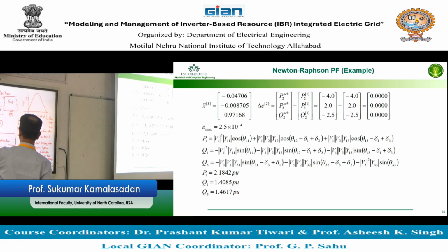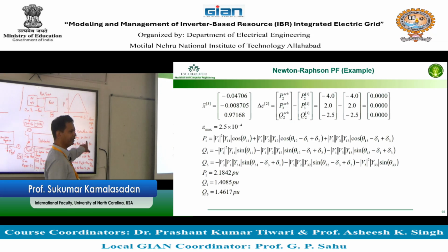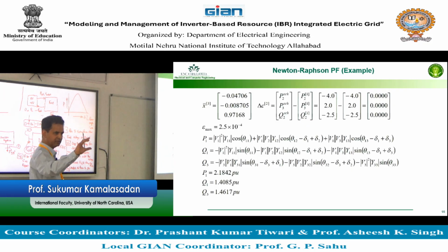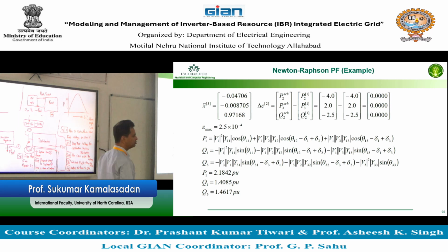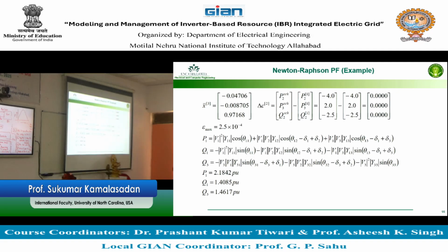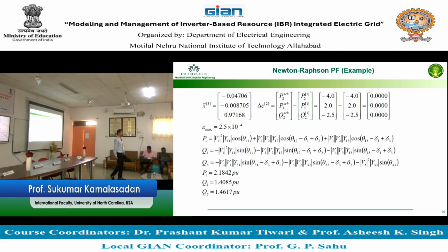And then repeat step 1, which is basically run transmission system power flow, find the bus voltage. Is the voltage on bus 2 the same as before or very close? Same meaning a small change. If yes, stop. If no, repeat. That's your procedure. Try that and we can look at it. I think you should be able to do it because we did both power flows.